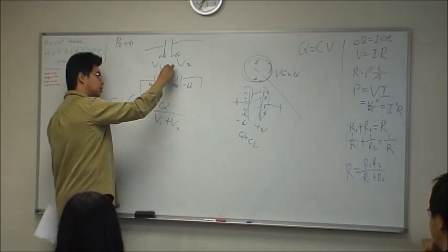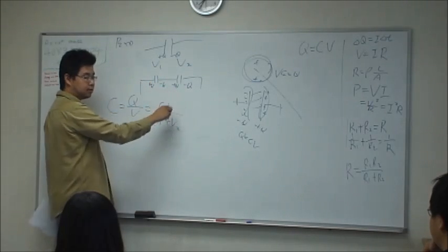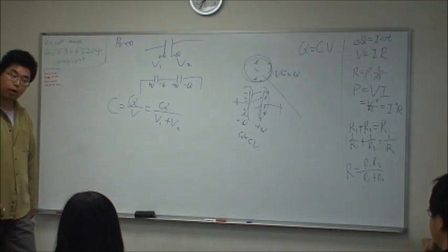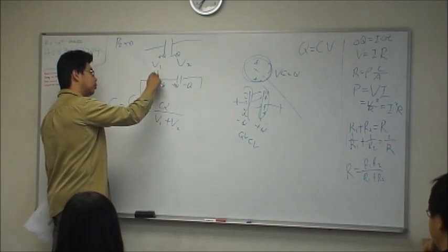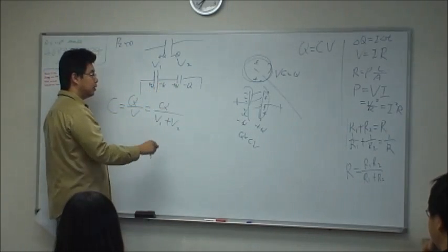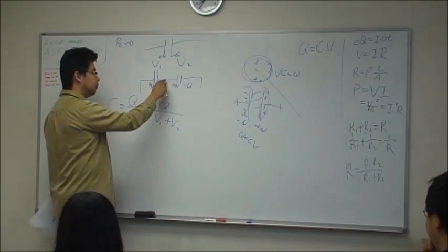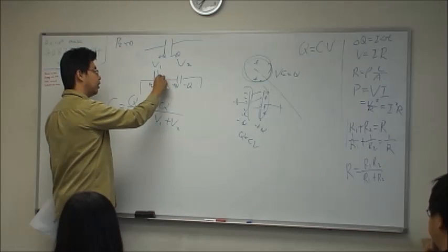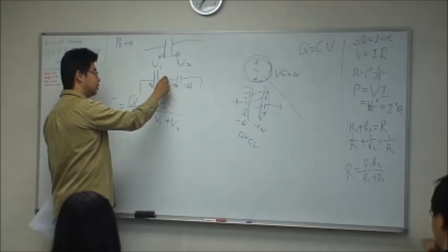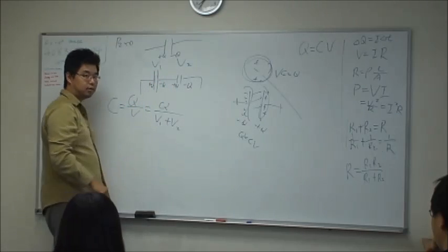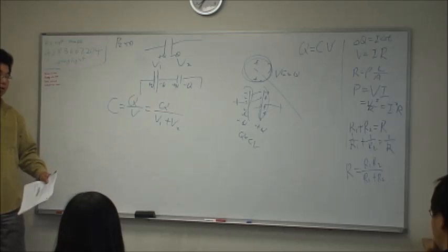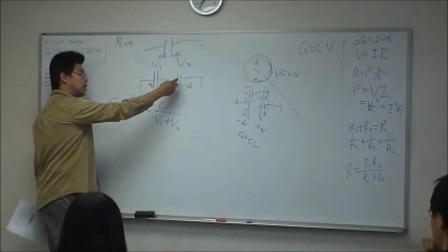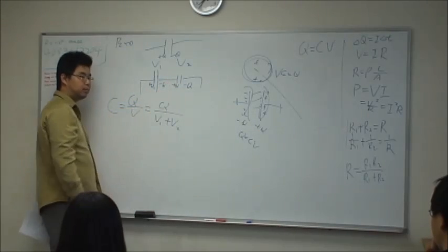In the middle, they sum to 0. Or put another way, since this is a capacitor, no current really flows through it. The only thing that changed is that the charge-neutral capacitor will have some positive charge go this way or negative charge go this way, so they just redistribute the electrons, but nothing more is introduced into the middle part. Okay?